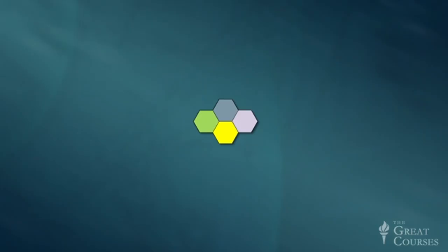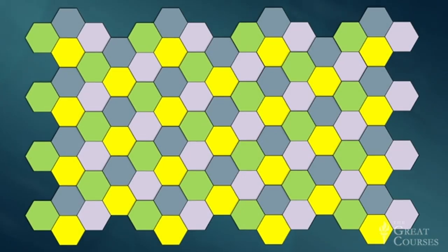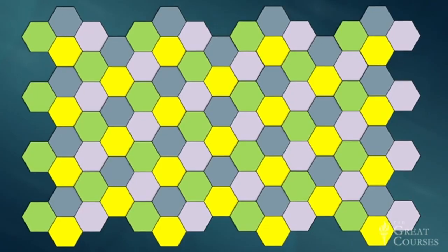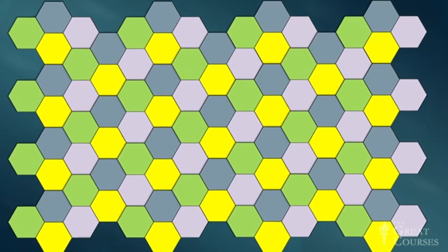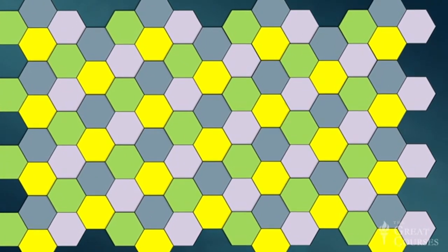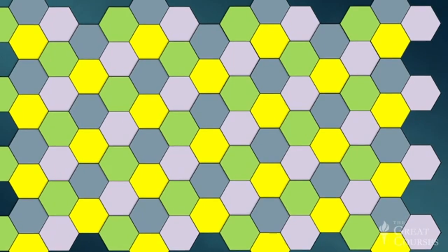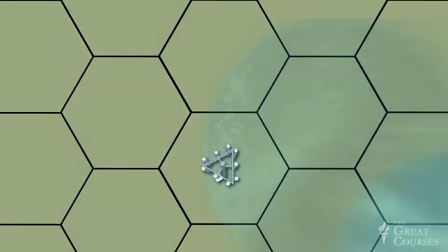One response to these challenges has been simply to use more efficient cellular reuse patterns. For example, this one is based on a 4-cell module, which still provides a buffer of 1 cell between each pair of cells operating on the same frequencies. This simple change allows for the use of 75% more frequencies per cell, with a corresponding increase in the number of users. However, the smaller buffer between the common frequencies also requires the use of antennas with more precise control of their coverage areas to minimize the likelihood of interference.